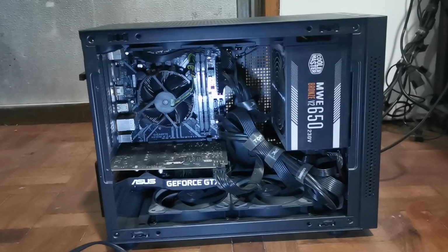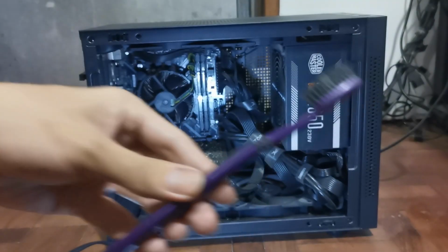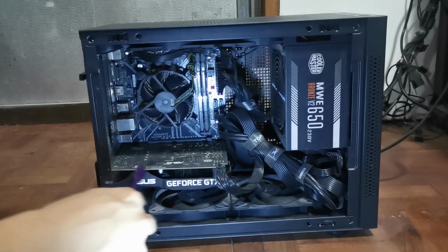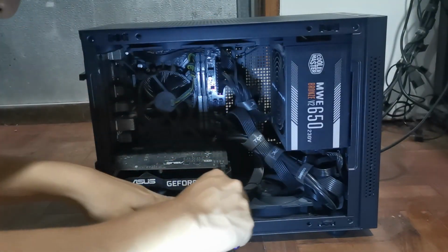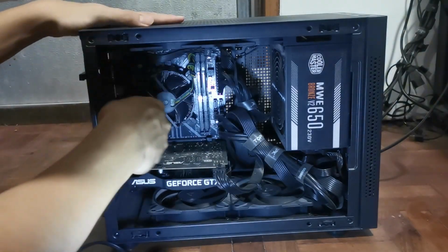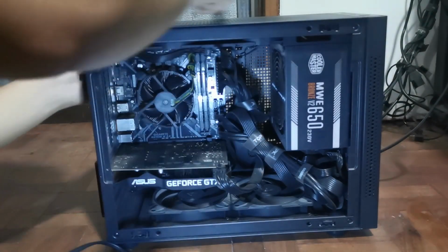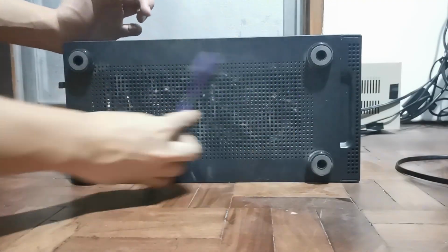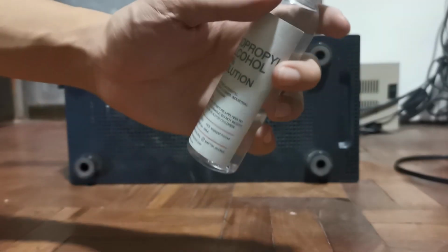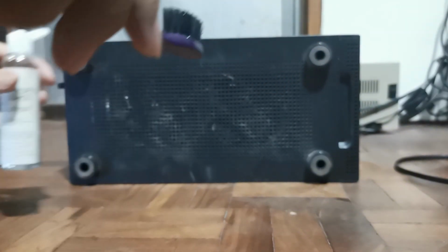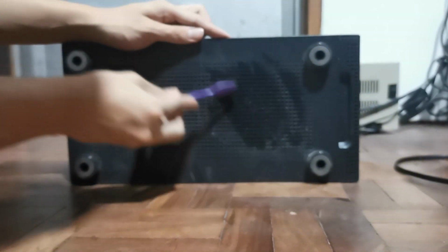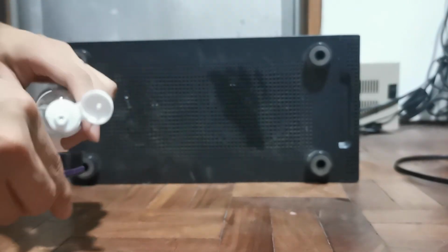Once you can no longer see any dust flying around, take your toothbrush and scrub the walls of the case and blades of the fans to remove any remaining dust. Aside from the motherboard, you can scrub most of the components as long as you do it lightly. If ever you find them difficult to clean, add some 99% isopropyl alcohol onto the brush to help break down dust and debris. Once finished, wait for about an hour for it to dry.